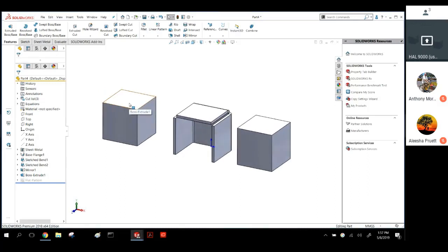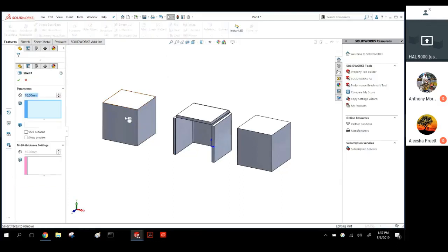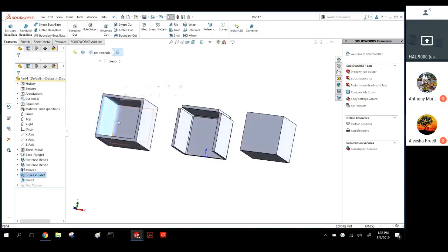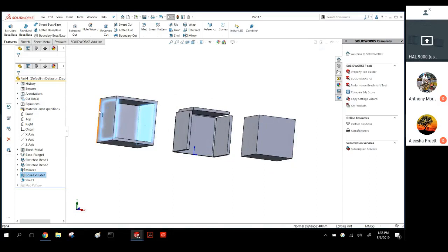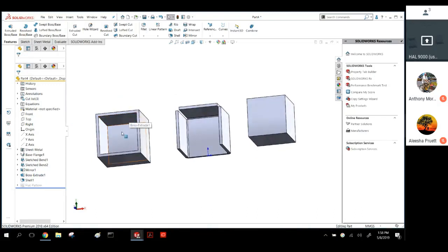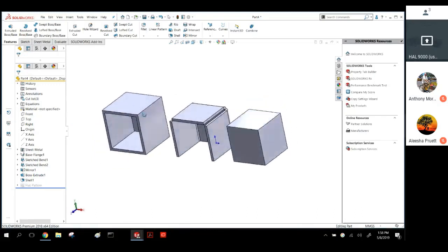There's 2 ways to create these 2 solid boxes into a hollow box. One is using our old friend shell. Pick this face, I put in the thickness that I'm after. I want to shell this to the outside, and now I know this box fits in a 40 by 40 cube. Or a 40 by 40 cube will fit into this box. However, this box is not going to unfold because it doesn't have a tear down the side of it.